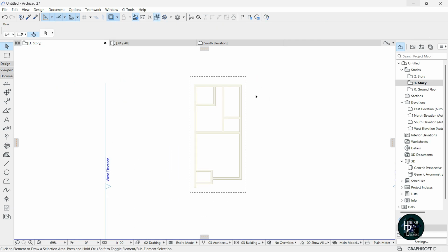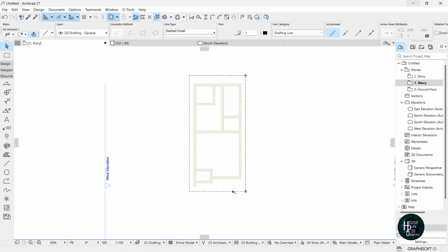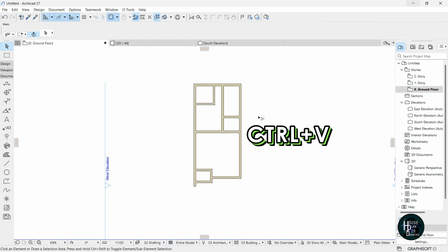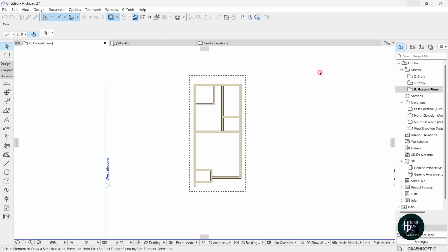Okay, now we're going to have something as perfect as this. This is going to be the cantilevered area of the drawing, and this should be shown on the ground floor plan. So I'm going to click on it. Okay, hold down shift, click this, press Ctrl C on my keyboard. Okay, go to the ground floor and press Ctrl V, then just click outside the box, and I'm going to be having that shown on the ground floor.